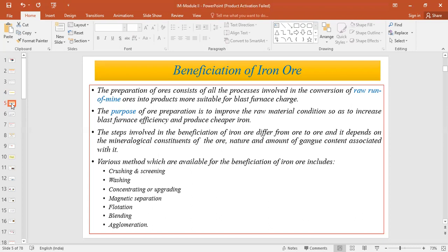So, the end product of the comminution process is iron ore in the form of lumps as well as fines. These lumps we can charge into the blast furnace as an iron bearing feed material. But fines, even though they have the same metallic value, the Fe content, we can neither transport nor charge into the blast furnace. It's difficult to transport the fines because they will fly away, and they will create a problem in the permeability of the bed.